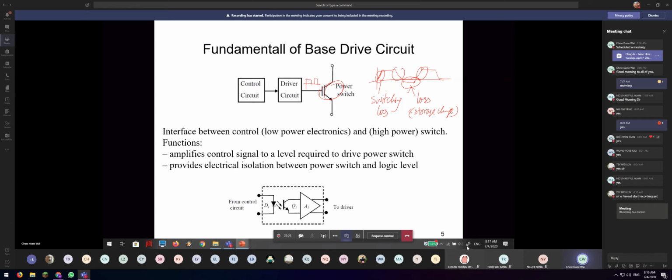All right. So the interface between the low and the high side can be isolated using the optocoupler. Basically, this optocoupler works exactly like a normal BJT, just that now it is wireless. They use light as a medium to control the high power side. So basically, it works like a variable relay, or adjustable relay in general.